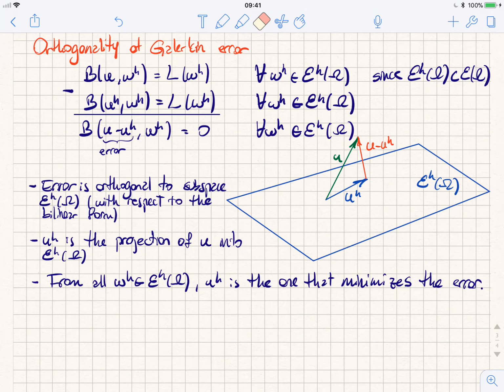Okay, so let's move on to the finite element discrete equation. So this is what we're going to do now. So far, we are in a discrete dimensional space, but that doesn't mean finite elements, right? We said that you can actually take basis functions that act on the whole bar, right? And that is the basis for the Rayleigh-Ritz method.